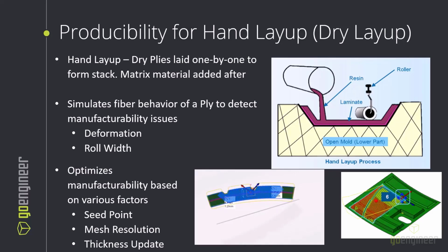And here we can see in the results we have a few different features. So here we see this blue mesh. The blue mesh means that the deformation of the plies has not exceeded our angular limit that we've set. Here we see some yellow mesh. It's still in the realm of being okay by spec, but it's getting to that breaking point. It's a checking limit to keep an eye on. Whereas the red is in a failure zone and we need to compensate for that failure.